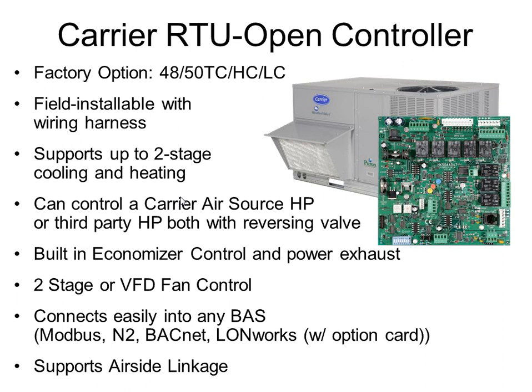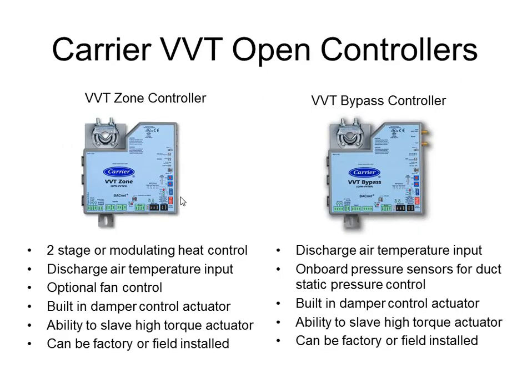And airside linkage is Carrier's pre-canned program that allows this controller to communicate with the VVT zone controllers to read their space temperatures, their set points, their damper positions, all it needs to know in order to respond properly. That's all pre-programmed from Carrier. And Carrier actually bought out Parker when Parker first developed VVT, so they've been doing this for 20, 30 years now. All of that algorithm is just built in, ready to go, ready to be programmed. So I'm sorry, configured.